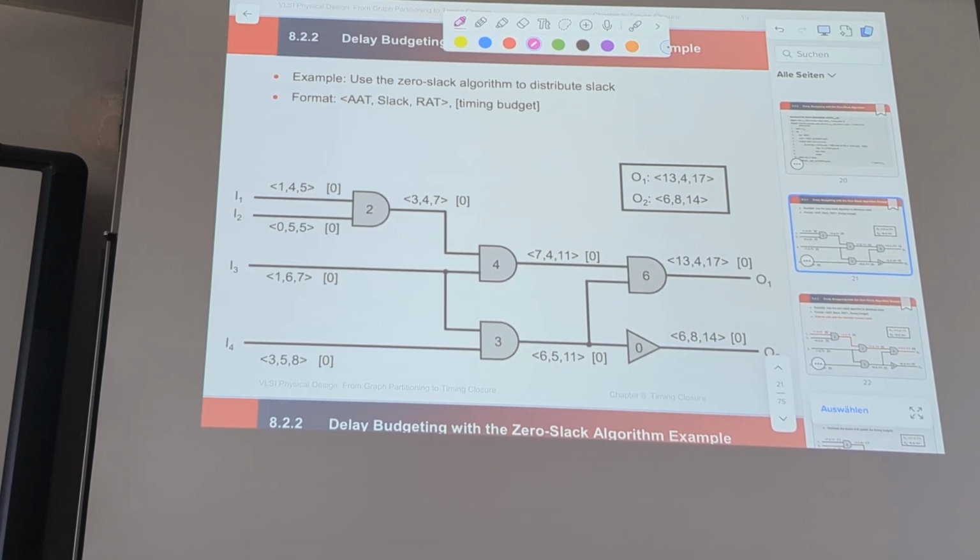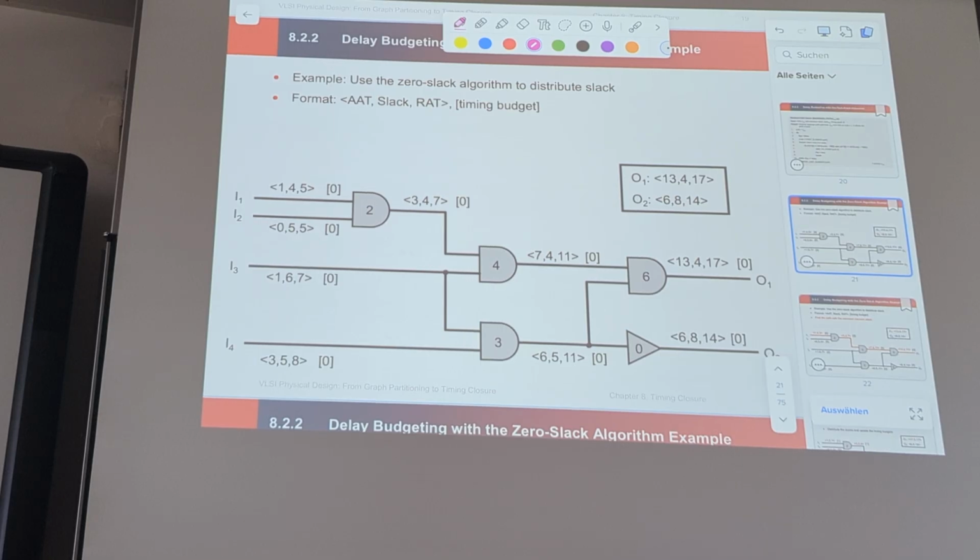Where are my options for placement and routing? Which cell can I move further down? Which need to be closer together? We know from static timing that this is our critical path. So we could look at this path and make it really, really fast. But maybe by doing that, we kick away our second worst path, and that will then be violated.